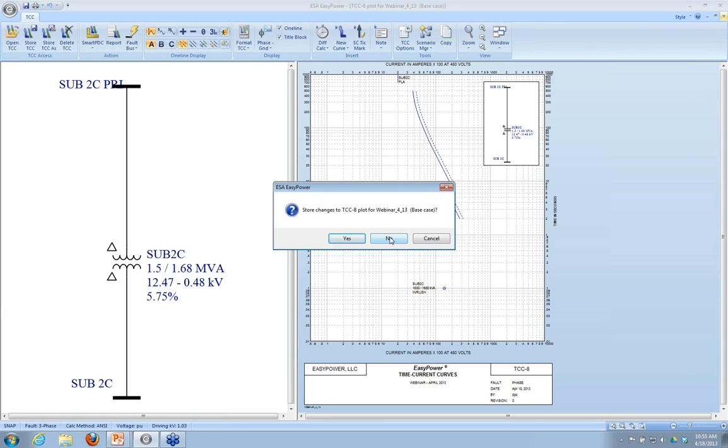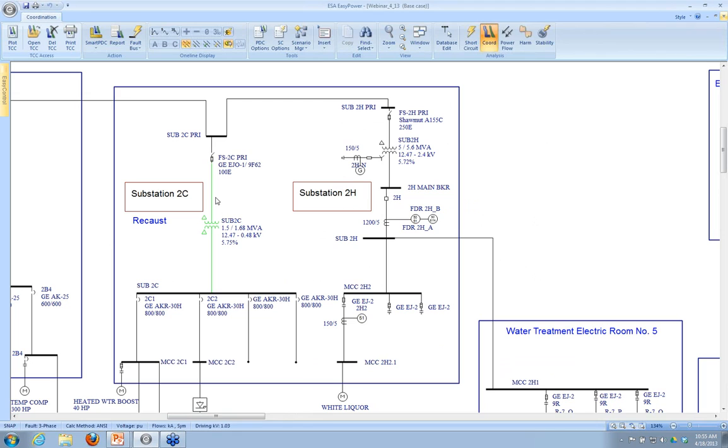So again, that 58% curve only applies for delta-Wye transformers. It's only for ground faults on the secondary side. And it's only for use in comparing the primary protection to that shifted curve for the damage protection.